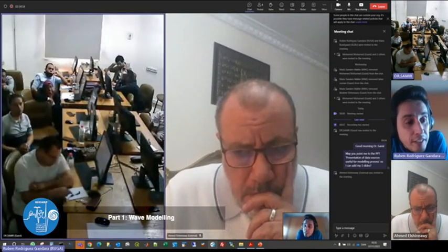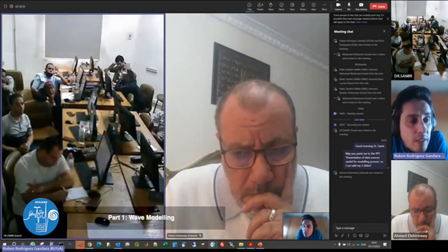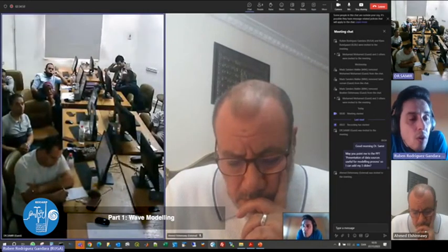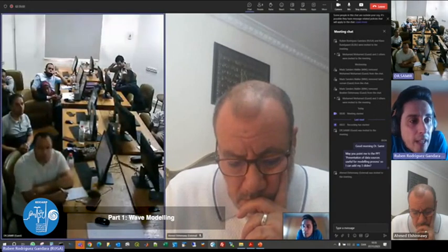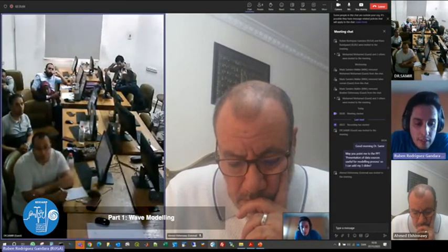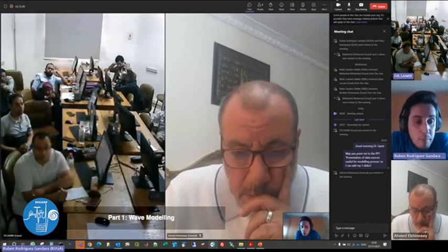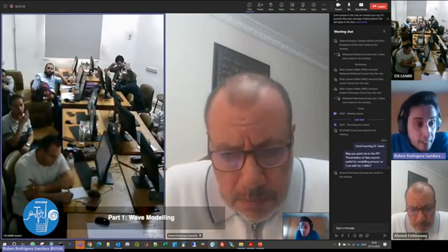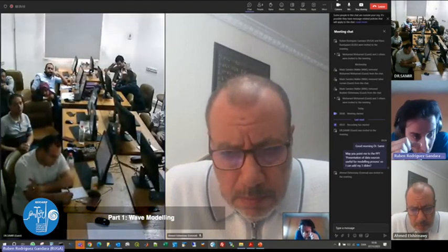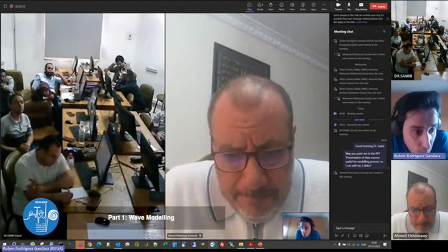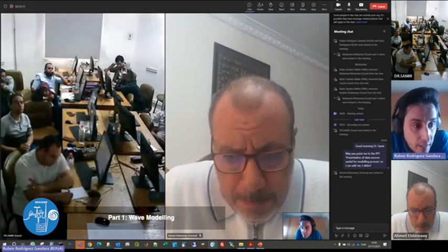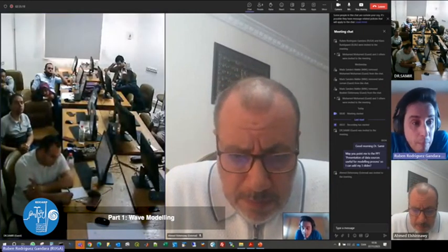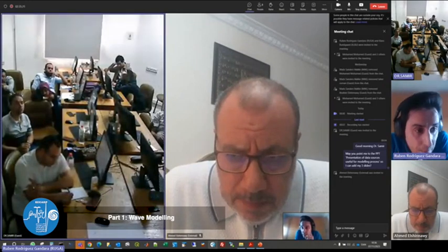And when you're interested in a local model, a small model near a harbor, or you want to take data from a regional model and create a local model of, let's say, a harbor or a beach, and you really want to see the effect of the currents on how the waves break in there, because your model domain is going to be very small, then you will be able to make use of the quasi-stationary approach. But again, please compute this quick number that I told you.